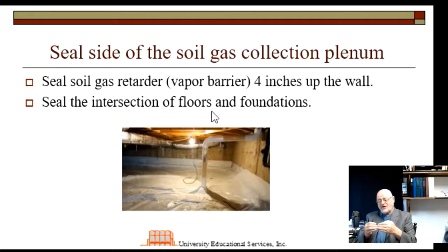That is, while the concrete looks really solid, there's a lot of space in there for the radon to actually percolate right through the concrete, through the empty spaces in the concrete. Now, it's much more difficult for it to percolate through concrete than it is obviously through air. So the concrete does produce a pretty good barrier.